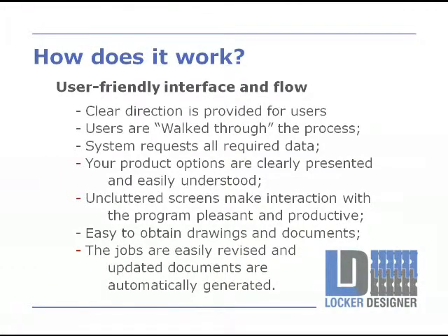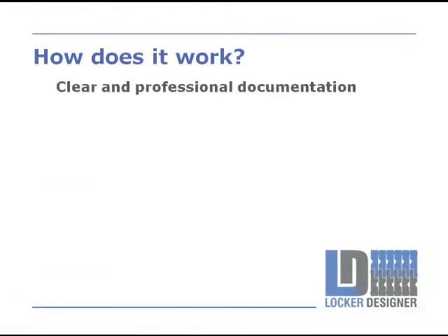This means that if you were on site or if there was some sort of change that had occurred, maybe there was a miscommunication and you issued the drawings, sent them to the client, and they said, oh no, this wall is really over here, or this wall is this long, or we can't have lockers on this wall because of XYZ. You would be able to go in and immediately make the changes to the job in the program. It's a very quick process. Hit the print process button, and immediately a fresh set of documents reflecting all the changes would be given to you. Clear and professional documentation.